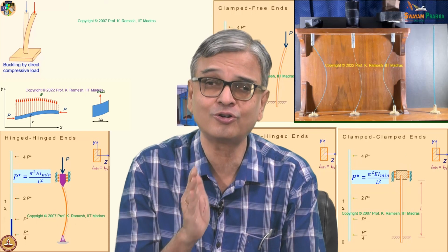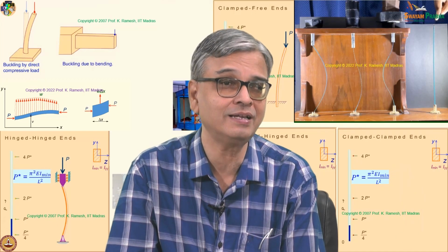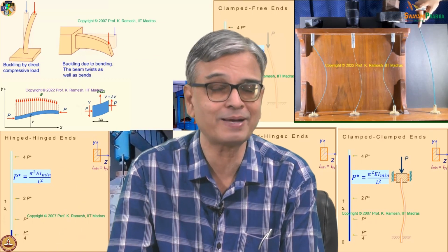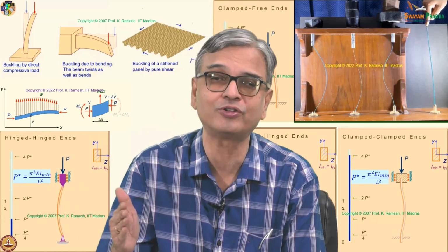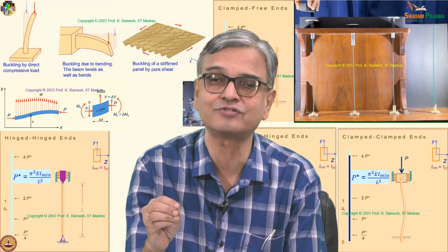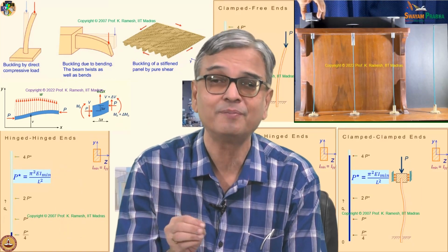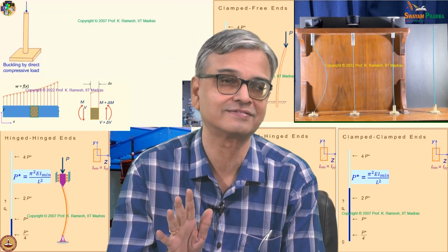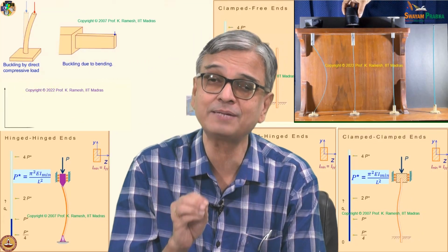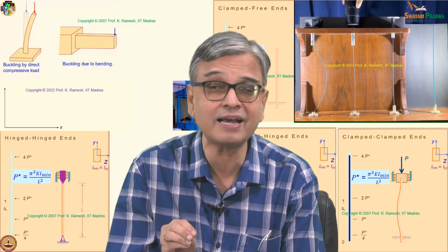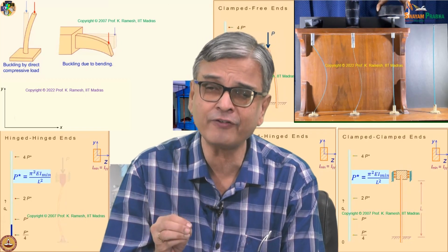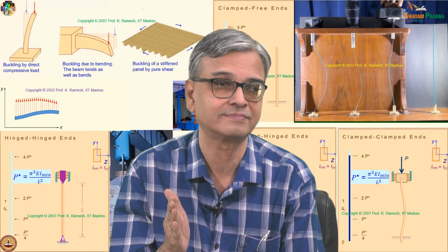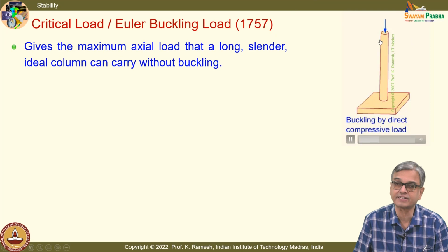See, in this course, to make our life simple, we have said we have an elastic continuum. Our mathematics, we could develop it so beautifully. When delta x goes to 0, there was material available. But real materials, how are they? They all have defects. So, one of the perturbations that can precipitate buckling can come from inherent defects on that column. See, I have a circular cross section.